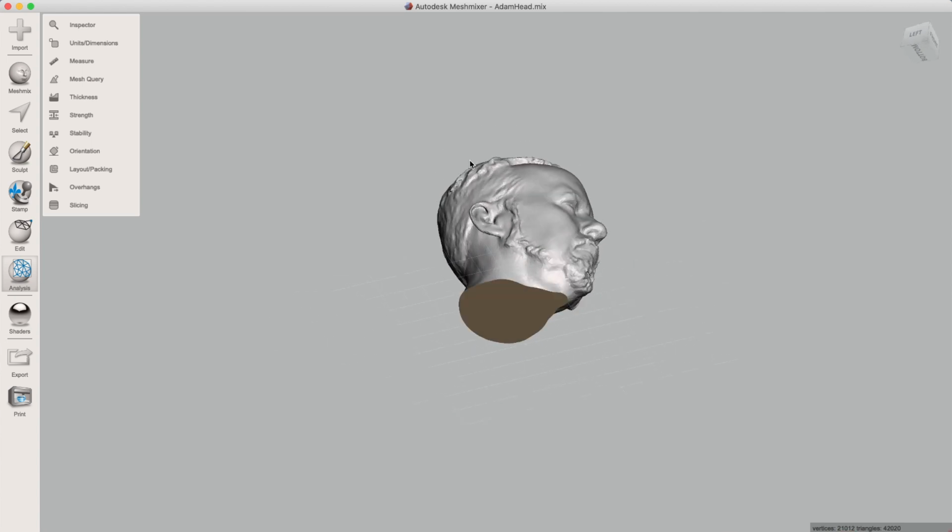Now we need to establish the peg hole inside of the Lego minifigure head. Now, the best number that I have come up with so far is 4.9 millimeters. It generally gives you just enough friction that things will snap on. Now, if you are doing resin prints, they are not very forgiving. And if you don't do the 4.9 or 5 millimeters, what ends up happening is you press the head on, it's going to be a little too much stress and it's going to pop or break the head. It's going to fracture like a little piece of glass. And you don't want to do that. So, make sure you do 4.9 millimeters.